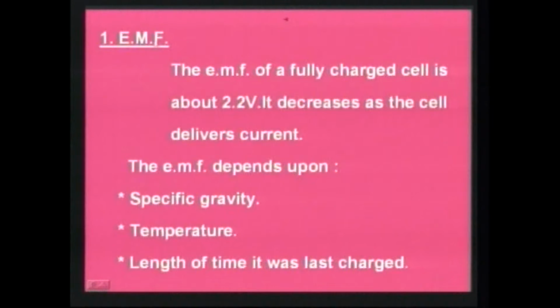EMF or electromotive force. The EMF of a fully charged cell is about 2.2 volts. It decreases as the cell delivers current. The EMF depends upon the specific gravity, temperature and the length of time since it was last charged.